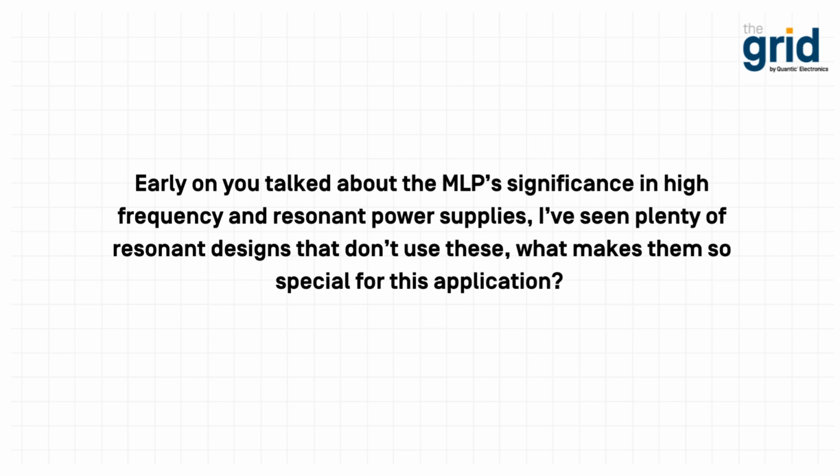However, you might need to include extra capacitors in parallel in order to meet the ripple current requirements, or in order to meet the ESR requirements. So by doing that, you're significantly increasing the overall size of your converter. So when size, weight, overall efficiency are critical, the multi-layer polymer proves to be the best solution.